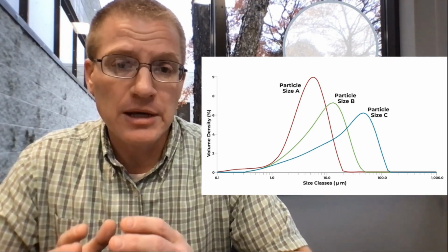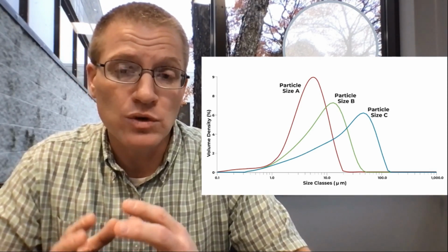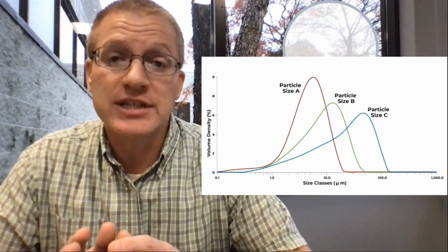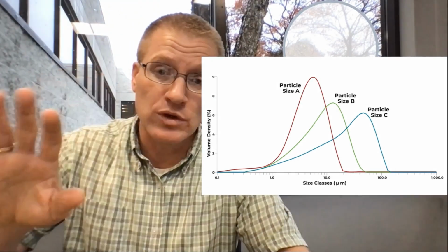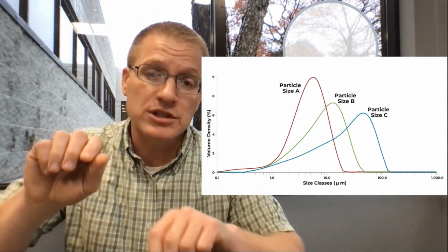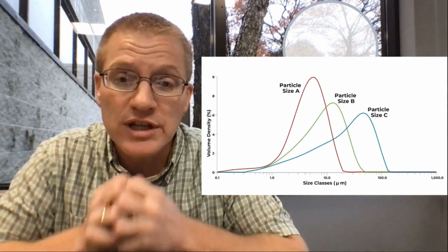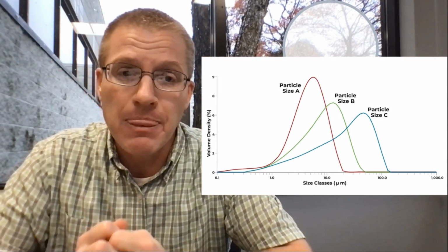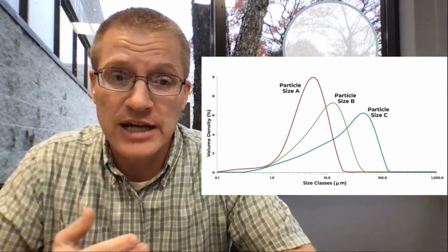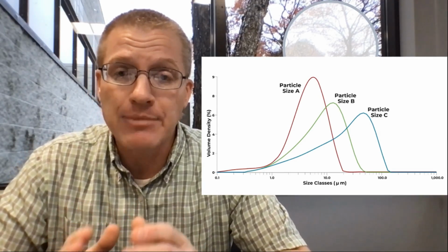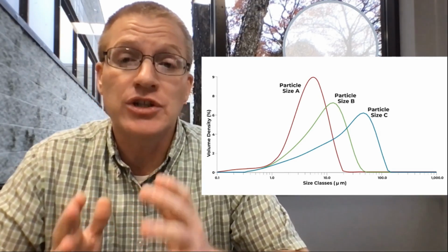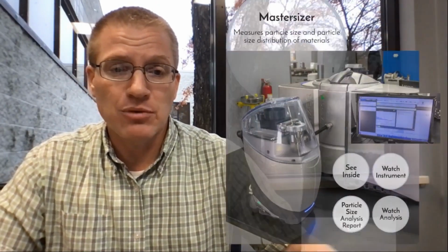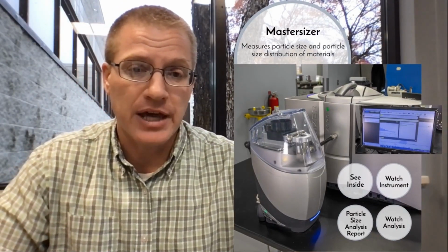So when we're formulating a material, we're looking to accomplish a very similar appearance as you saw in the marbles earlier. We have really big ones, and smaller ones and smaller ones and smaller ones, so you get really tight, intimate contact and really good packing between those, so you get really good particle size contact. So we're ultimately optimizing particle size distribution using different sizes in order to get that optimization of properties. And you're going to see a really great example of that in just a minute.